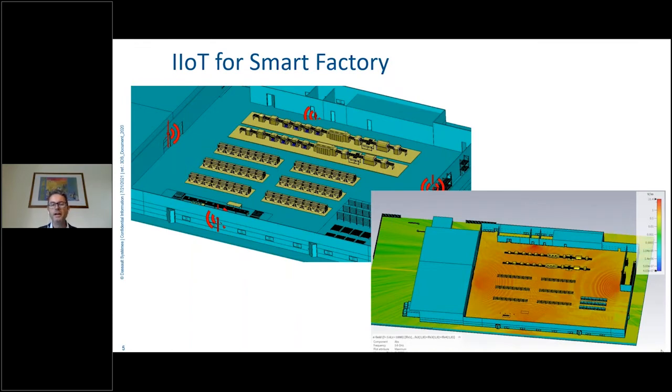And you can see here below, in red is where the electric field in volt per meter is very high. And in yellow, and in green even, it's too low. And you see leakage through the window over here. And you see near the docks there, the signal is not enough. It's not red, it's yellow. So what you can do, you can optimize the position of the 5G antenna. You can study if there is a coupling with some metallic piece nearby, so that you can really optimize the coverage of your 5G signal.